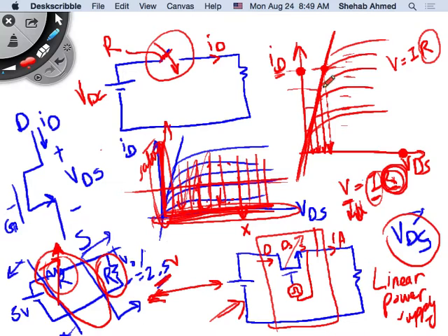The relationship between them is such that the slope here is always fixed. And this slope is actually the resistance of the MOSFET. You probably heard of RDS on, right? The drain to source resistance. That's something you study in 325. You don't need to know the history, but the RDS on is basically the resistance of this switch. So now I'm only utilizing RDS on across the switch, which is a very small value.